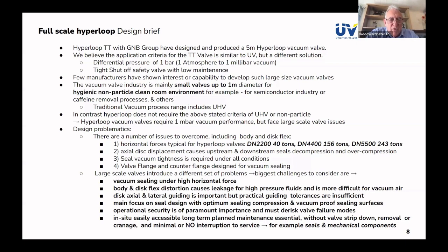Finally, the whole question of maintenance. You see, with such big valves, we can't be putting these valves in and then expecting to remove them from the pipeline or break them down or strip them down for maintenance or failure repair. These valves should be designed for zero maintenance, and they certainly will have a very long life with very high cycles.